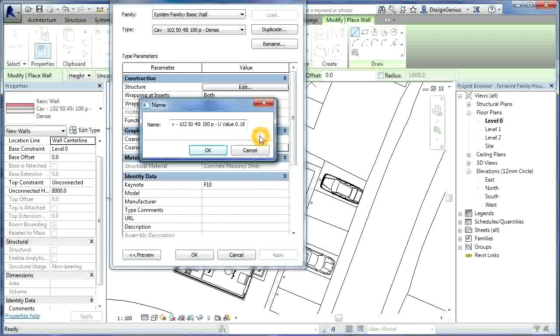Right. So if I leave that as a U value, if you remember what we did, we said the fiberglass insulation was going to be 41, and then the block work was 120, and the insulation before the plasterboard we said was 49.5.